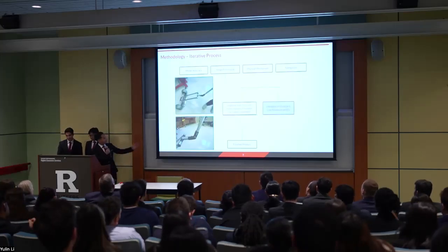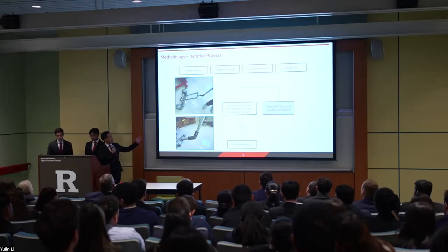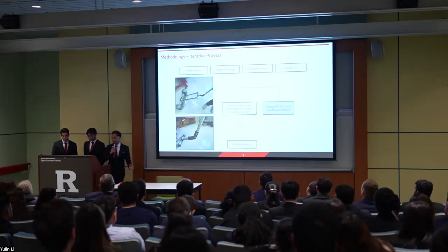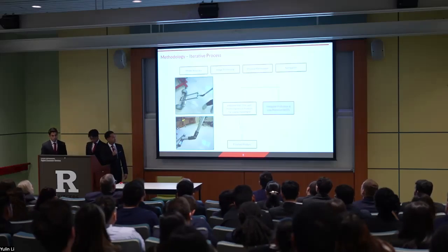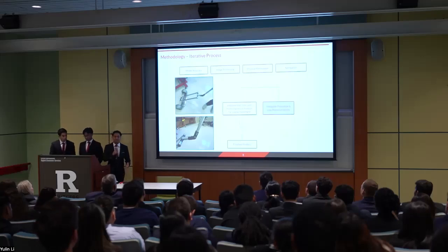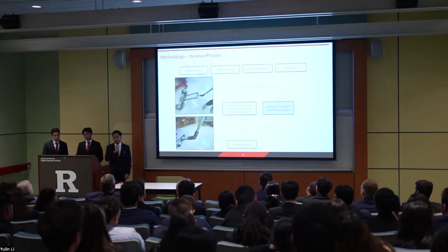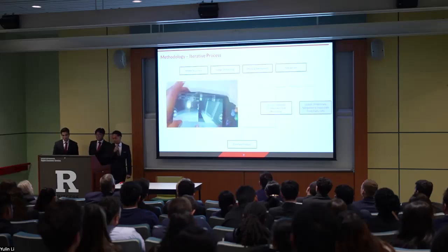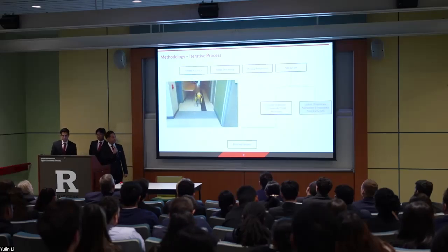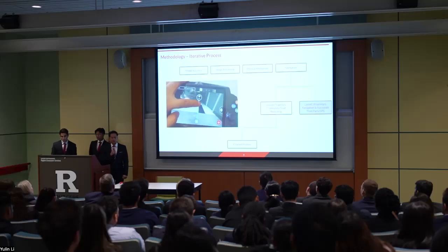As you can see, we designed essentially what looks like a sand rake over here. This is what's attached to the dog. At first, we came up with an infeasible prototype. It was essentially a soccer net on the back of the dog. However, that ended up having low maneuverability. So with this, we created essentially a swivel joint mechanism that has 3 degrees of freedom, so that it has lateral movement. And onto the trajectory commands, we noticed that Spot lacked proprietary navigation services.